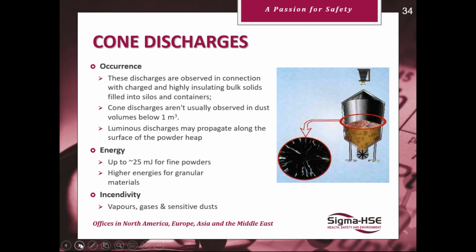On investigation, there was a Japanese engineer on site at the time who said there was a probe in there with a small piece of plastic on it. That plastic would have given a brush discharge to ignite the powder. Well, the powder had an MIE of 10 millijoules, so it wouldn't have been that. But the silo was full of insulating granules.